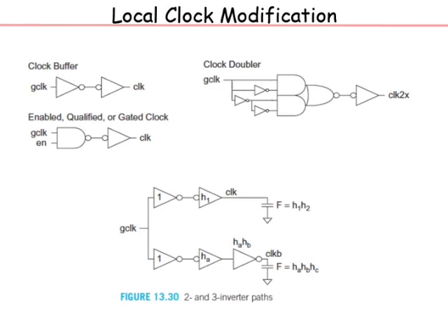One approach could be to reduce voltage swings, so the global clock could be a signal with lower swing. Another approach could be that it runs at half the clock rate, and then when it comes to the local one there is a clock doubling. This logic circuit doubles the clock, where the global clock is running at half the rate and you get both edges. You can work through the logic later on to see how it works. So that could be another approach. The global clock now is running at half the clock frequency.